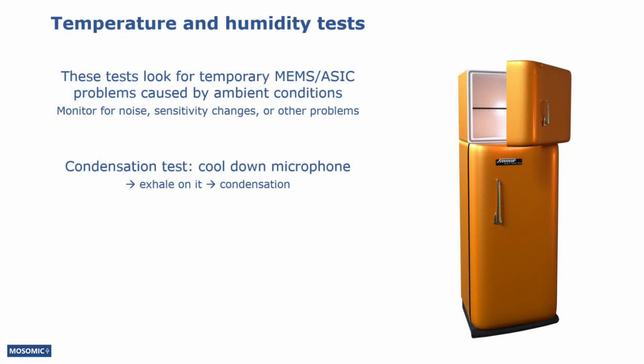The temperature and humidity related tests look for temporary problems in the microphone caused by different ambient conditions. In the condensation test, microphones are cooled in a fridge, taken out and immediately exhaled on slowly. The resulting condensation on and in the microphones should not cause noises or other problems.